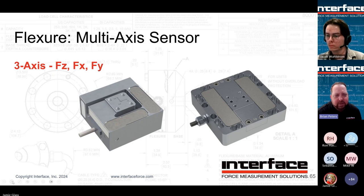So it works. There might be some compromises in terms of deflection, stiffness, as well as maybe introducing a little bit higher crosstalk, right? Because every single element there is going to respond to that force. So that's one way to do an FZXY shear, is to have them all connected. The one on the right there has a center section that's bolted in to discretely measure the vertical, and then it interacts with 2 different sections beneath it to then be able to transfer the X and Y. So it's just a different approach there, whether they're all in one or isolated as much as possible from a multi-axis standpoint. Next slide.